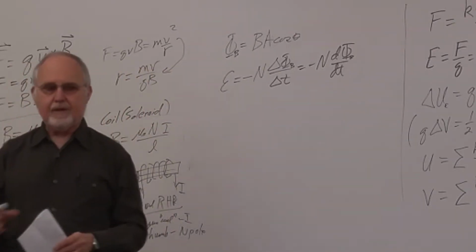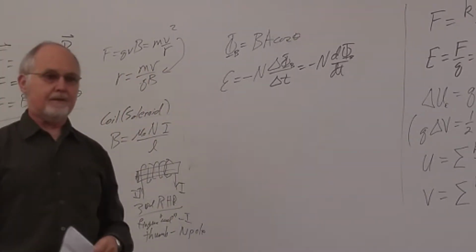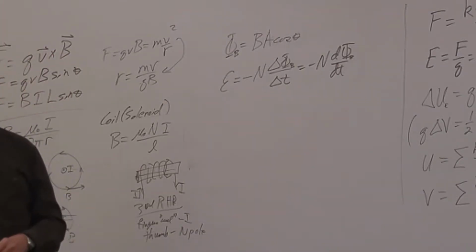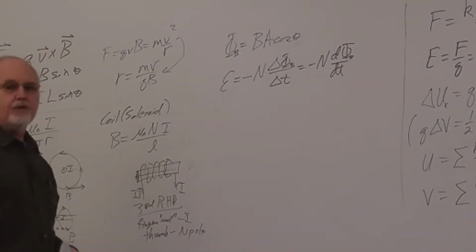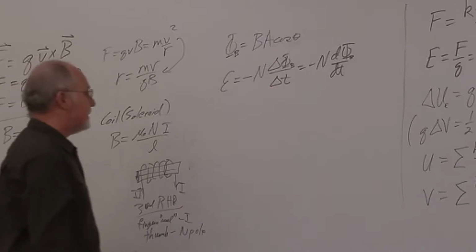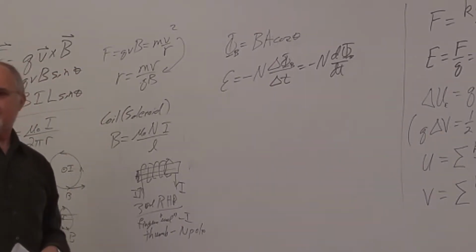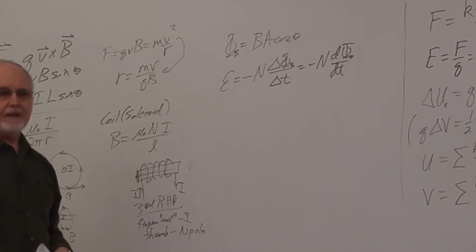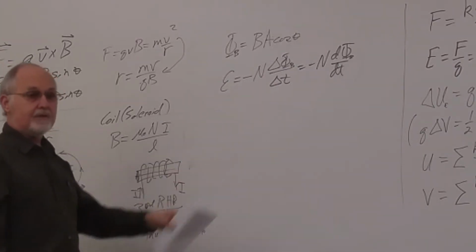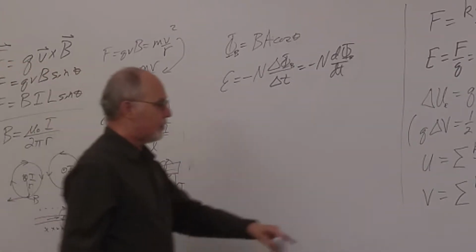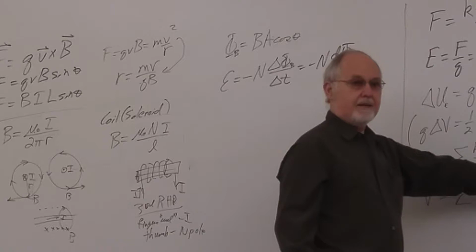So if any of those are time-dependent, then you can take a derivative to find the induced voltage at some time. There was that question on that test about what was the maximum current, and you're given the flux as a function of time. So you took the derivative to find the voltage, and voltage was current times resistance.